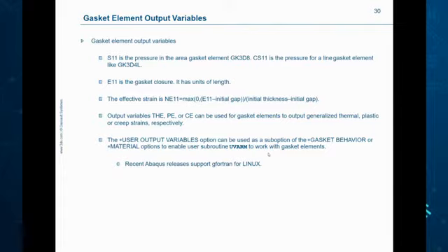Gfortran, of course, is something that comes with Linux. So if you want to do subroutines, you don't have to worry about getting the iFortran stuff. You can use Gfortran. But you have to have the version of Abaqus that supports Gfortran.